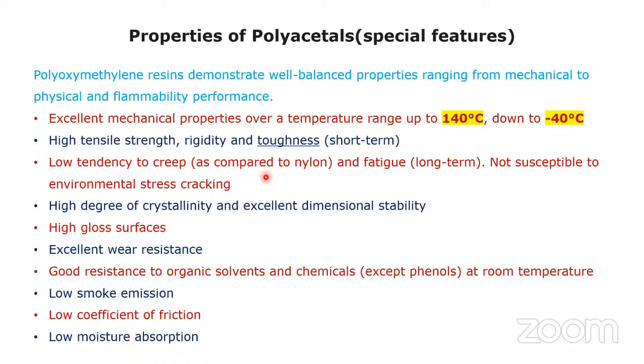Yes, actually, sir, within the cooling time, if you are removing it from the tool before cooling, obviously it will shrink. Actually, it requires some time. Within that time, if you are removing it, then the shrinkage happens. Yes, correct. If some more time is given, then it doesn't happen. And the packing should be increased. It is obviously dependent on your injection pressure and whatever cooling time you have provided. Yes, sir.